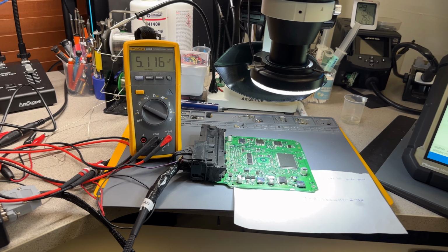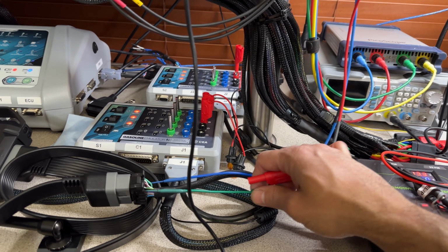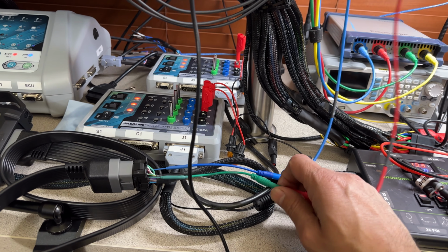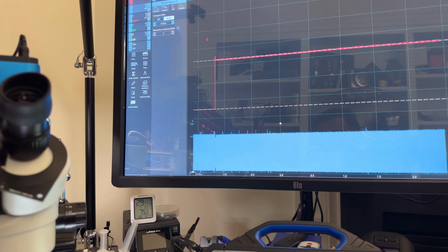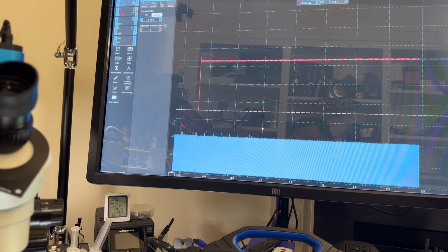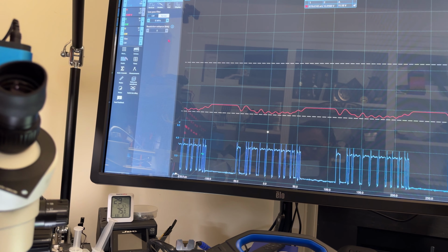And we have a glitch on the COM bus, which I'm going to move now that we finished this. I want to show the entire bus connected since I'm here again for my records and his. So in this case, I'm going to have to now come back and change the time base to microseconds, right? 50 microseconds should be, yeah, somehow good.